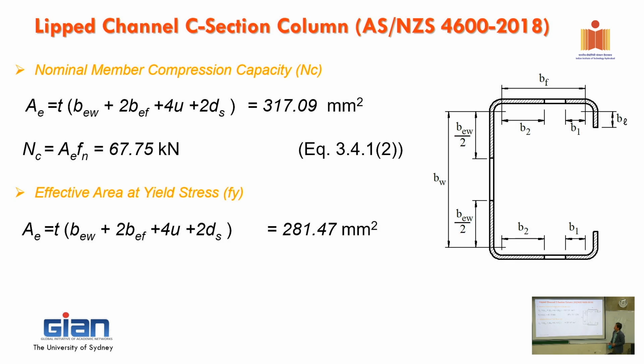And of course, the next one is when you calculate the area with the yield stress, getting the maximum Fy. As I explained to you before, you got all the help, the lateral restraint, everything. You make sure that you force the column to just buckle in the section. It doesn't matter along or whatever, because you restrain that already. So that's why now we got Ae here, based on the yield stress.